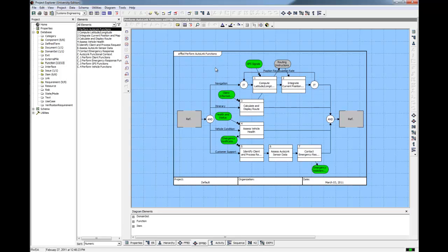Align commands are also available for both horizontal and vertical alignment. Multiselect using the Shift-Click method all of the nodes you want to align, and click the desired alignment icon at the top of the diagram.